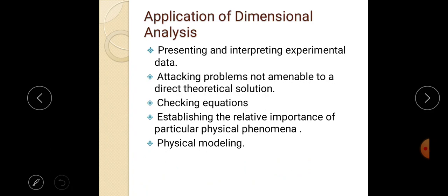And what is that dimensionless relationship? We can simply write CD equals a function of Re, where CD is the drag coefficient and Re is of course the Reynolds number. So we have reduced our 5 variable problem to a 2 variable problem with non-dimensional groups. We have seen in this instance that dimensional analysis has reduced the number of relevant variables from 5 to 2, and the experimental data to a single graph of CD against Re.